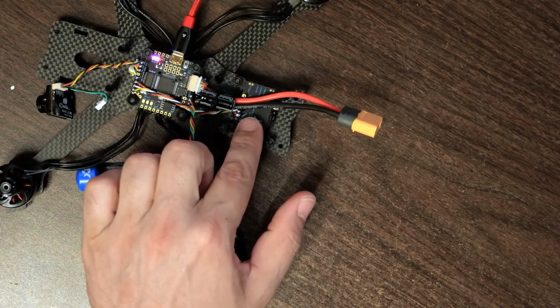It transmits on a certain channel. And if your video transmitter transmits on the same channel as someone else who's also flying, your signals will interrupt each other and you will both crash your quadcopters and be very angry at each other. So being able to move to a certain channel quickly and easily is the key to harmonious flying with others. SmartAudio also lets you change your output power.